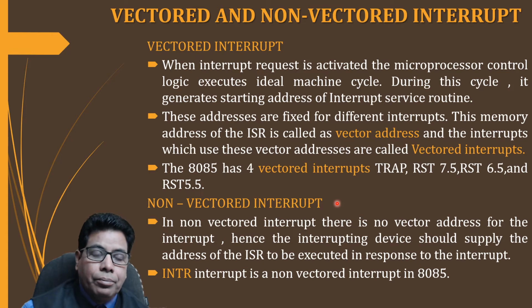interrupt vector table. Then for the non-vectored interrupt, there is no vector address, and so the interrupting device should supply the address of the ISR to be executed in response to the interrupt. Only one interrupt is non-vectored, that is INTR. So the INTR interrupt will supply the address with the help of the interrupt acknowledgement signal, INTA bar, using hardware. We'll see the details.